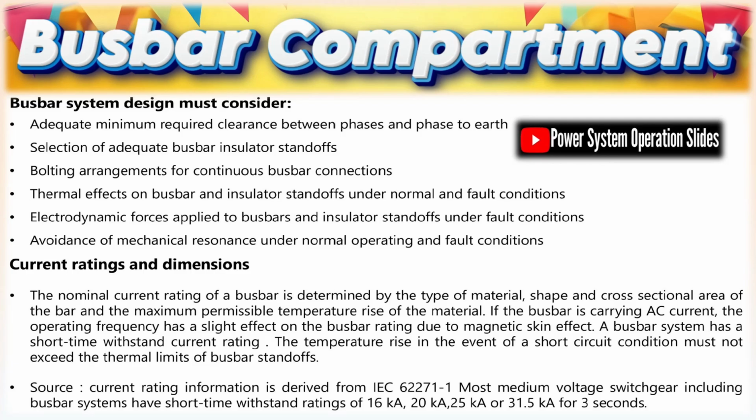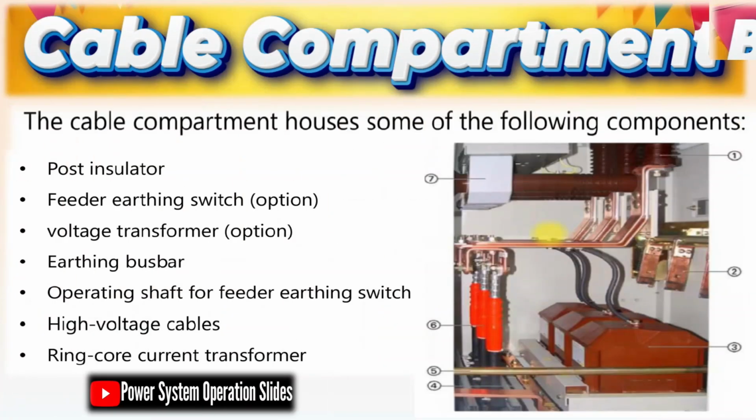Distance relay. Measures line impedance to estimate fault distance and protect transmission lines. Operates within defined zones for fast, selective clearing. Essential for long line protection.